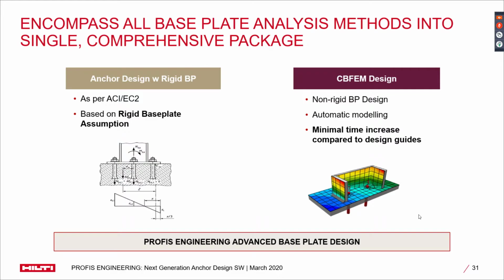Now, going back to the design of full connection in Profis Engineering, the offering we have implemented in Profis Engineering includes the following. First, the same anchor design with rigid baseplate assumption according to ACI or Eurocode. Secondly, we have included a finite element analysis module using what we call component-based finite element method, which can complete a full nonlinear analysis of a realistic baseplate behavior.